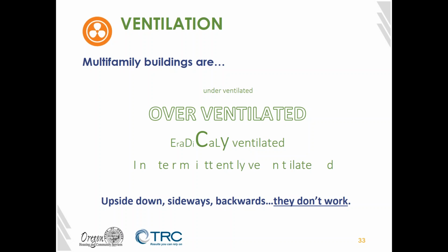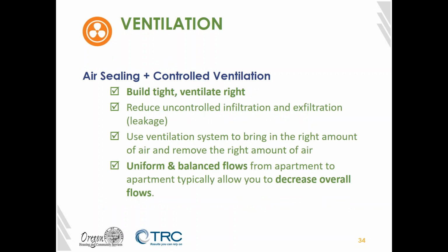So how do we fix this? What we do is air sealing and controlled ventilation. Hopefully, everyone on the call is an experienced building professional and has heard the phrase build tight, ventilate right. That is what we want to do. We don't want to just say, well, our building's leaky, so that's our ventilation, right? People have this misconception that buildings need to breathe. The ventilation system, that is the lungs of your building. It is doing that breathing. We need to air seal and then ventilate effectively.